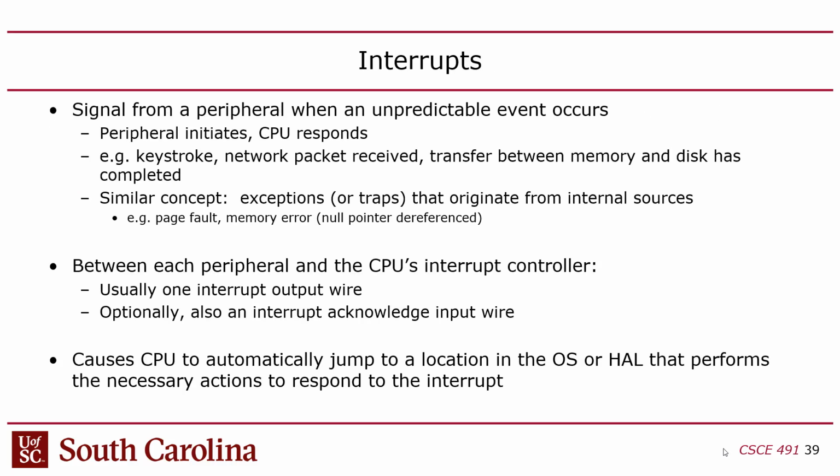Okay, so let's talk about interrupts. So I mentioned that programmed I/O is fundamentally based on the microcontroller determining when communication is initiated with the peripheral. But if the peripheral needs service from the CPU, or the microcontroller, right? The peripheral, like for example, if it's a network card and it receives a packet, or you hit a key on a keyboard, you need to get the CPU's attention. And this is assuming the CPU is not polling, not continuously monitoring the situation.